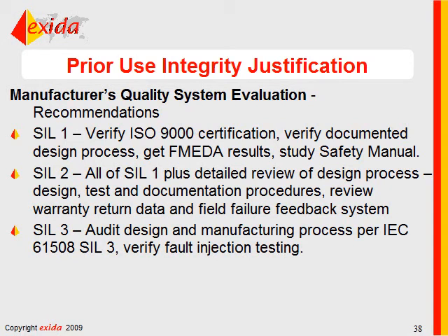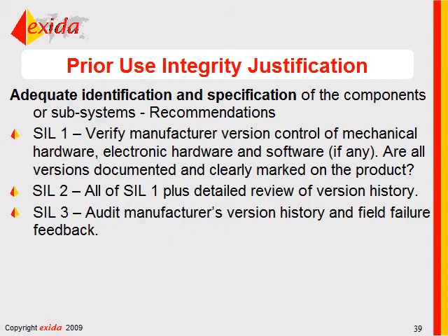For SIL 3, I would audit the design and manufacturing process per the standard. And the standard has roughly over 200 specific requirements of things that must be done in the design process. I would verify fault injection testing, because it's just shocking how many unexpected things come from that particular type of testing.